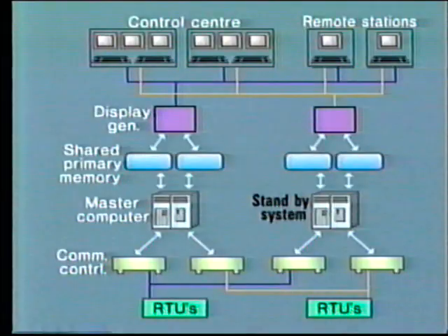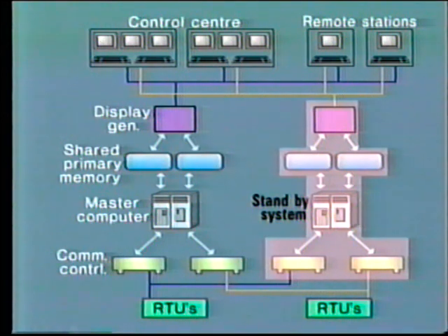On most major control systems, it is usual to duplicate all of this equipment by providing a hot standby, that is, a redundant master station. This unit is up and running and ready to take over immediately if any failure is detected in the online computer system or peripheral equipment. Here we see a typical arrangement. Note that the standby system completely parallels the online system.